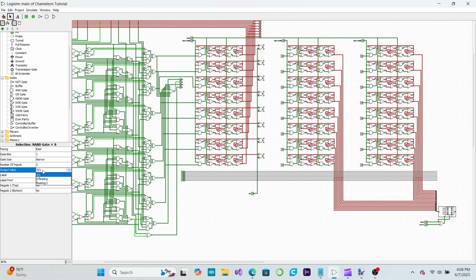In order to get this to work in Logisim, we need to set each of the NAND gates' output settings to 0/floating. This will make it so that the gate only pulls its output low, and then when the gate is on, it simply does nothing to whatever wire it is attached to. This is a concept called open collector logic, and stems from the days when bipolar junction transistors were used more commonly than MOSFETs in computer hardware. I'll go ahead and label all of these NAND gates OC in order to distinguish them.